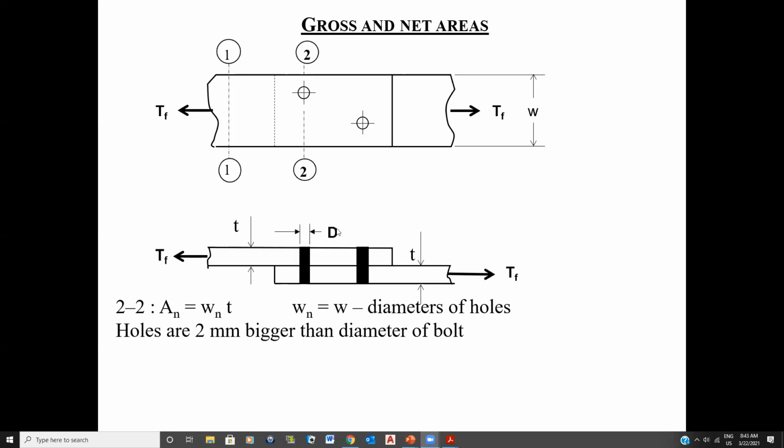On my drawing, I would say 2 20 millimeter bolts. That's what I need to be able to get my resistance, hypothetically. So I don't specify the diameter of the hole on my drawing. I just specify the diameter of the bolt I'm going to be using to make my connection. And of course, the guy that's going to be fabricating these two plates to be bolted together is going to make the hole to accommodate a 20 millimeter bolt.